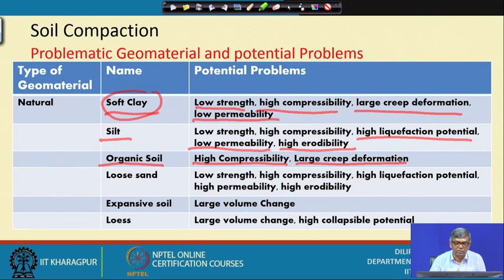Of course, strength also is low. Loose sand is generally good, but if it is loose and fine, then there is a problem. It will have low strength, high compressibility and high liquefaction potential.